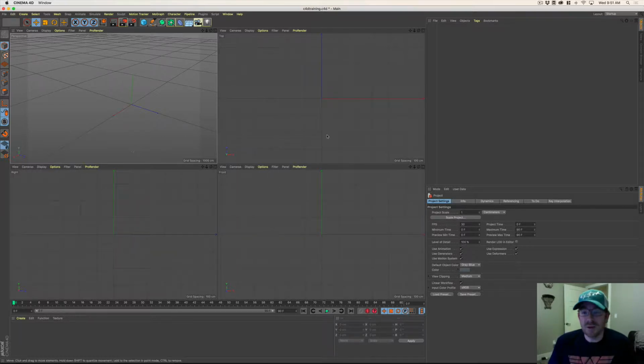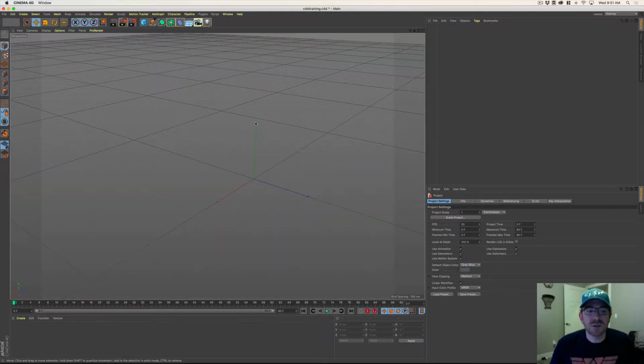Another way to do that without that button, keyboard shortcuts, or actually a mouse shortcut, is scroll wheel click. Your scroll wheel has a click to it. So I can get in and out of a view by clicking that view, and it takes me into that view. So we'll use that as we go. Using your 4-up view is a very, very efficient way of designing. If you're only using your perspective view, it's actually very, very difficult to get exactly what you want.